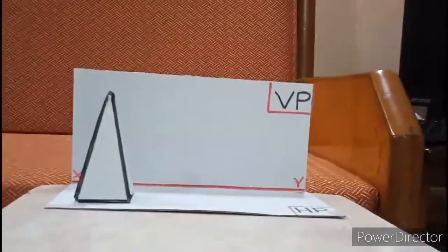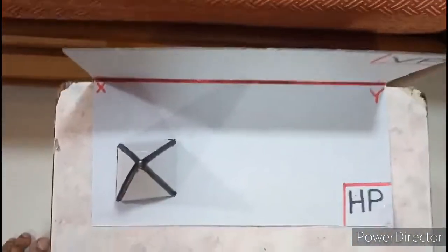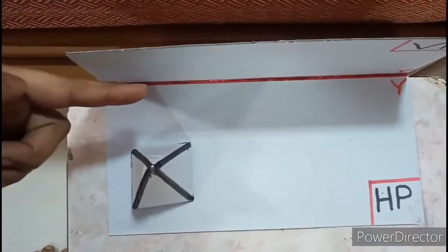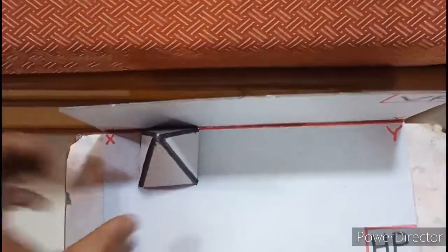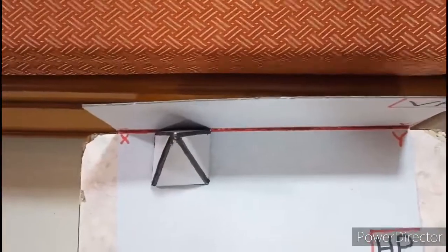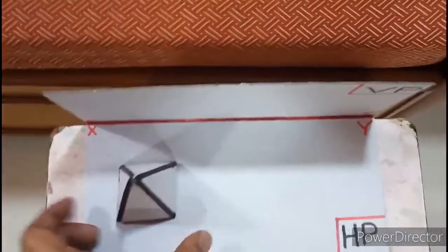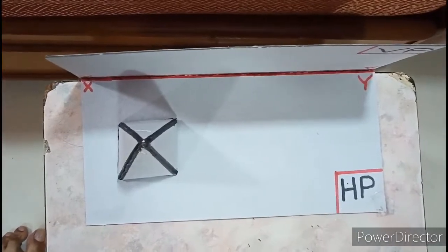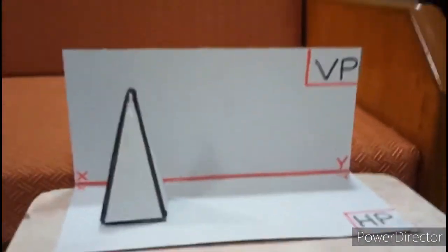Okay. So in the front view, you can see a triangle. And in the top view, you can see a square, perfect square with 4 edges, slant edges. And see, there is a gap from xy to this base, isn't it? It is not in contact, because if I make the base edge to come in contact, then the question will change. One base edge on VP also should be there. So that's why we need to leave a gap, because in the question nothing is mentioned with VP. Okay, so this is the top view where you can see a square with 4 slant edges and apex. So you should start from top view, and then you have to switch over to front view where you can see only one triangular face.